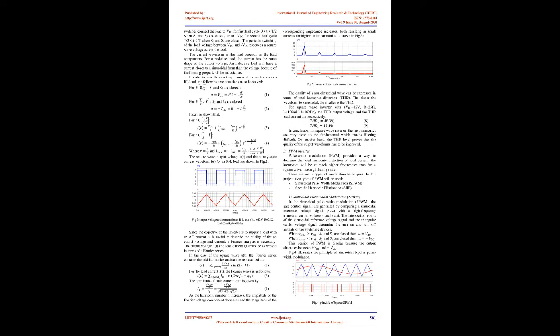2. Theoretical background. Inverters are circuits that convert DC to AC. The full bridge converter of Fig. 1 is the basic structure of an inverter. The switches S1, S2, S3, S4 in the full bridge inverter must be capable of carrying both positive and negative currents. Therefore, a feedback diode is placed in parallel, antiparallel, with each switch. The semiconductor devices T1, T2, T3, T4 must be fully controllable switches which can be turned on and off, such as BJT, MOSFET, JFET, IGBT, GTO, MCT.